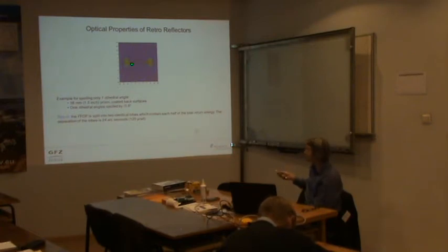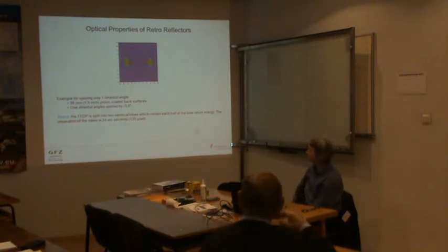But unfortunately, I told you, the pattern rotates together with the satellite. In case you rotate the satellite for 45 degrees, this pattern would be here. In case the station is still there, the station sees nothing. So in case the satellite is maneuvering and is performing some yaw steering, this method is not applicable.